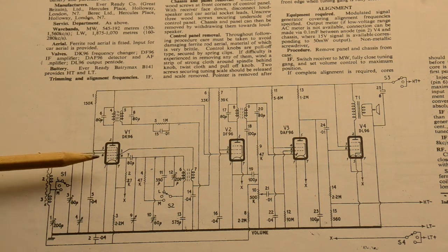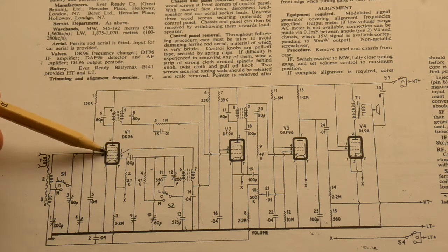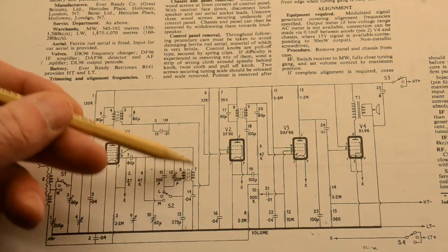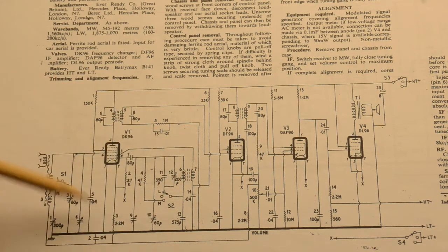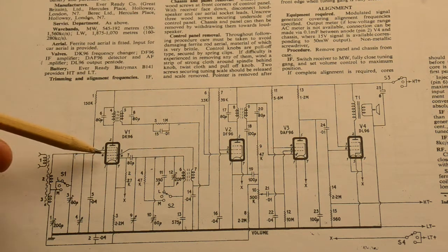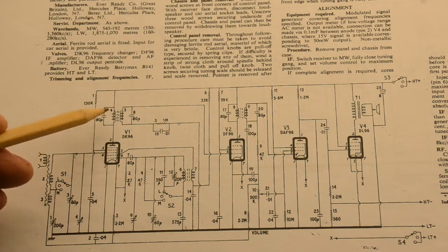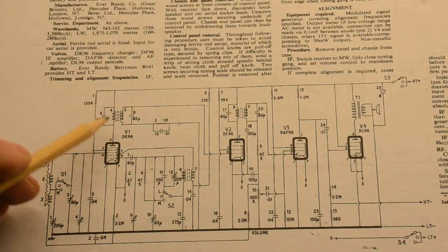This is actually a heptode, and it has a total of 5 grids in it, and they split up the valve basically to use one of the grids as an anode. And here we have the oscillator coil. So this portion of the valve works as an oscillator on its own, and it doesn't care what goes on at this end. Then if you feed the signal in through here, through the 3rd grid in this particular circuit, sometimes it's the 2nd, then that will be mixed with the oscillator. The output will be 465, 470 or whatever in the IF.